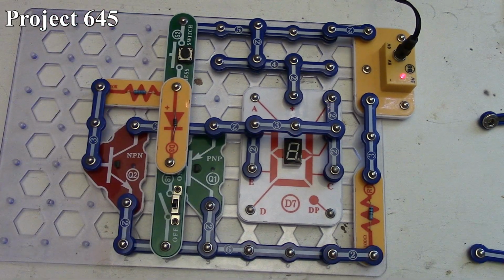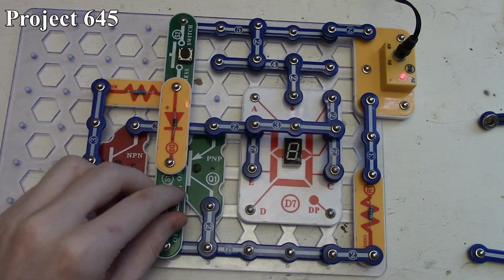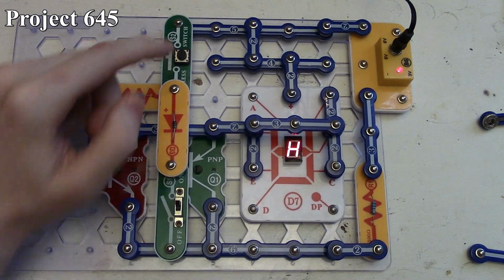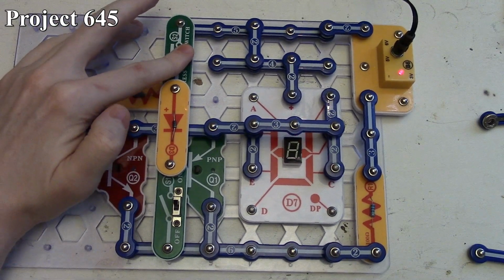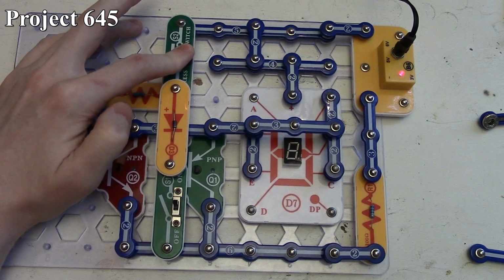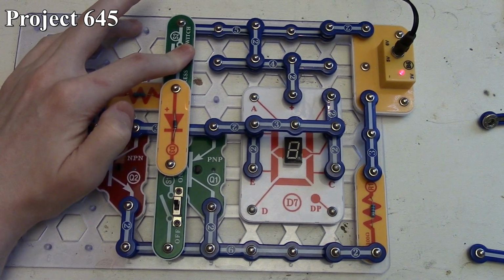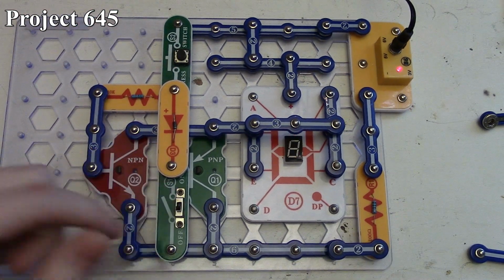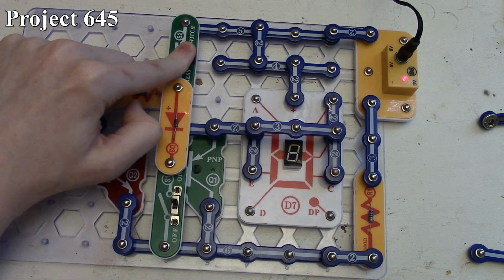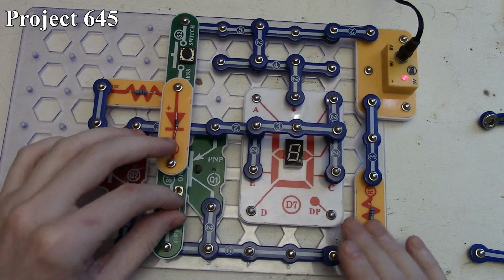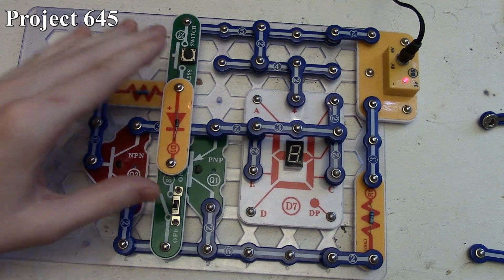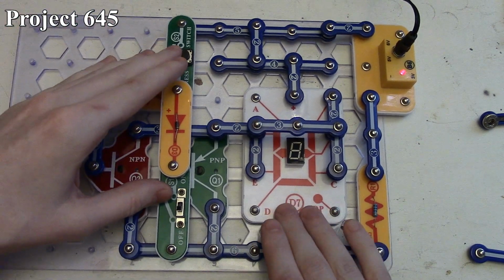So far it's behaving like a traditional OR. However, with an exclusive OR, when we have both our slide switch and our press switch turned on or both true, we now go back to a false condition on our output. And this is the exclusive part of the exclusive OR. Again, as I say, you can have either or, but not both. So in the case of an exclusive OR, either the conditions can both be false or they can both be true and you'll have a false condition.